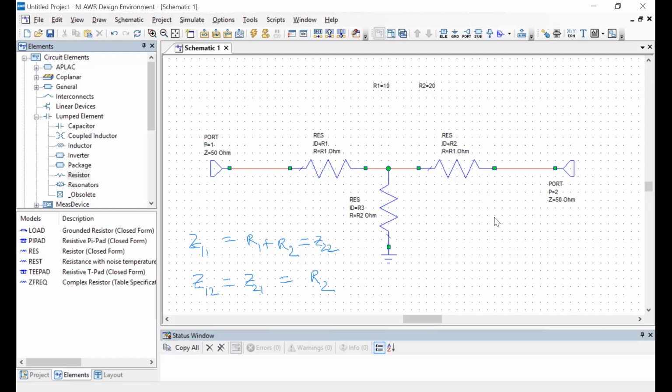So, Srijita, in terms of the fact that we want to use this as an attenuator, whose job is defined as something which attenuates the outgoing amplitude by some factor, what else is needed for this to be a good device? Needs to be matched at either end. Yes. Matched to? The ports here, port 1 and port 2, it has to be matched to both of them. Right. So port 1 and port 2, of course, are both 50 ohms.